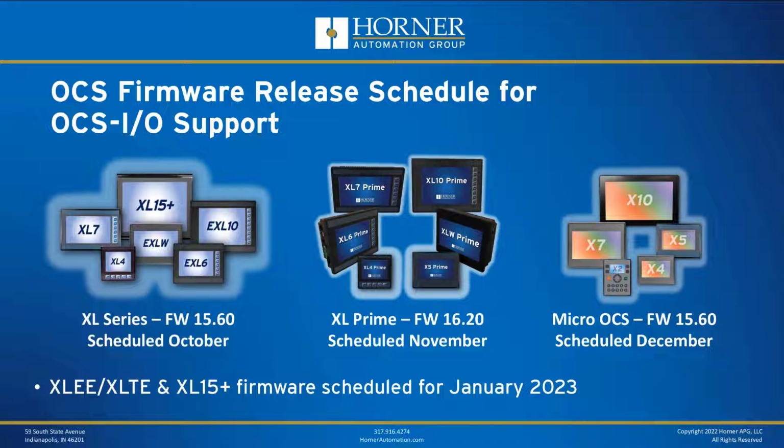Okay, I had one more question, in case there's some others that are just getting ready to type theirs now. We had a customer ask about millivolt mode. He noticed that on the universal analog inputs, we're supporting millivolt mode. And he wondered whether that would be appropriate for load cells or strain gauges, or whether he'd be better off with some sort of a weigh controller or a strain gauge amplifier.